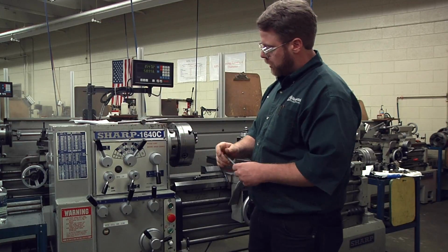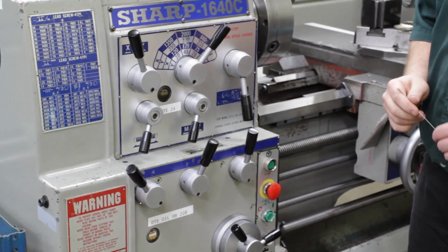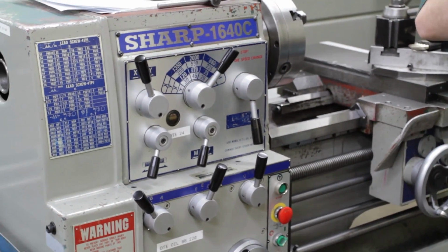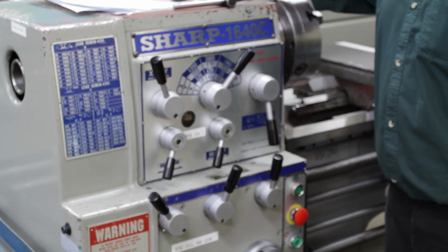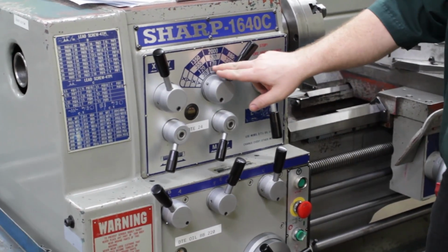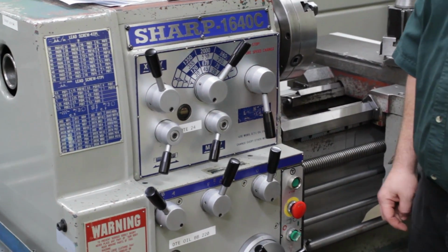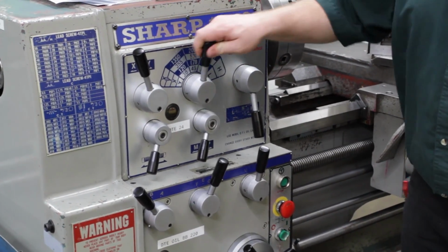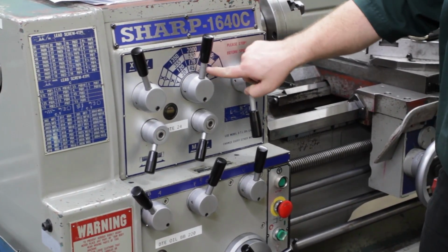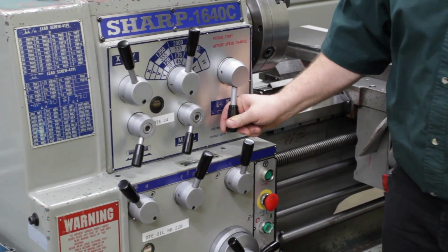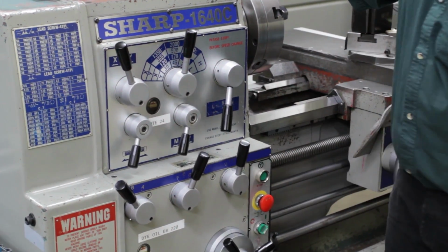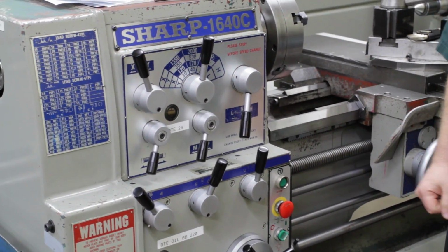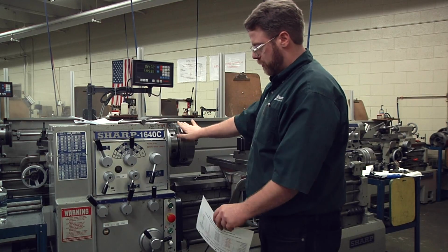On the lathe, you only really have 12 different speeds you can run. It ranges anywhere from 20 to 2,000 on this machine. Our calculator says we need to run 182 RPM. The closest one I have is 170. If I'm going to go 170, I have to put this handle in the middle position. That is in the low range, so I need to put this in low, and this has to be an X, which that handle already is. That'll set your RPM for this machine.